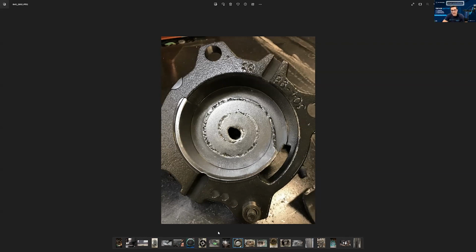And you really want to take the time to figure out what causes the migration to cause that slug, or that flooded start that leads to the slug, and that slug leads to the electrical failure. So there is this process that you need to look into to figure out the root cause of it. These are the things that you want to look for, right? Flooded starts are something that, once again, on scrolls, you don't see by looking inside those compressors.